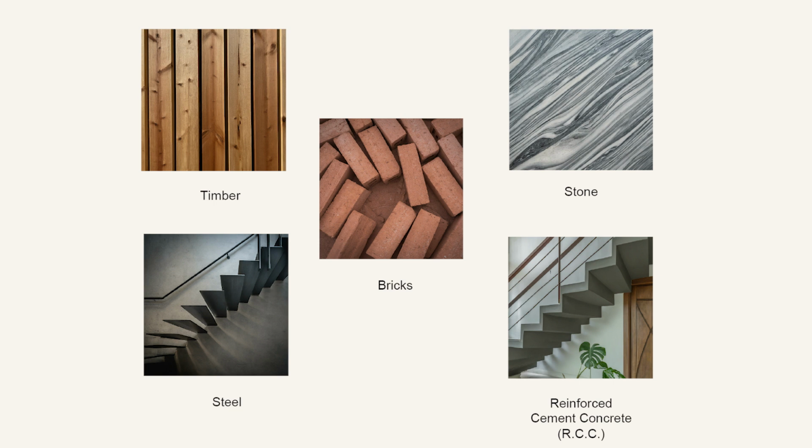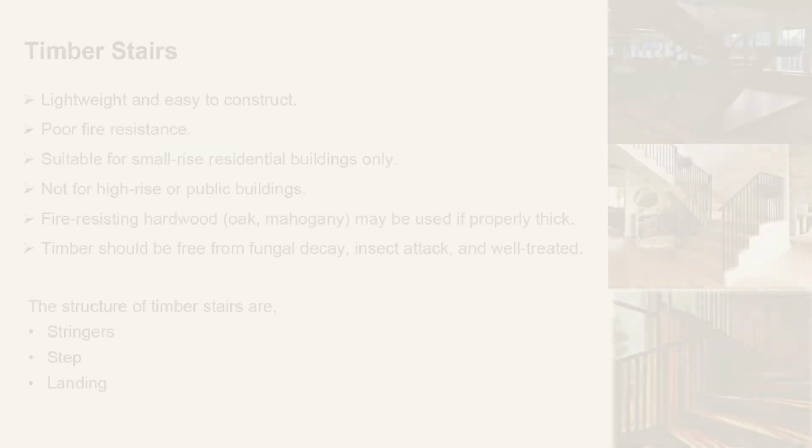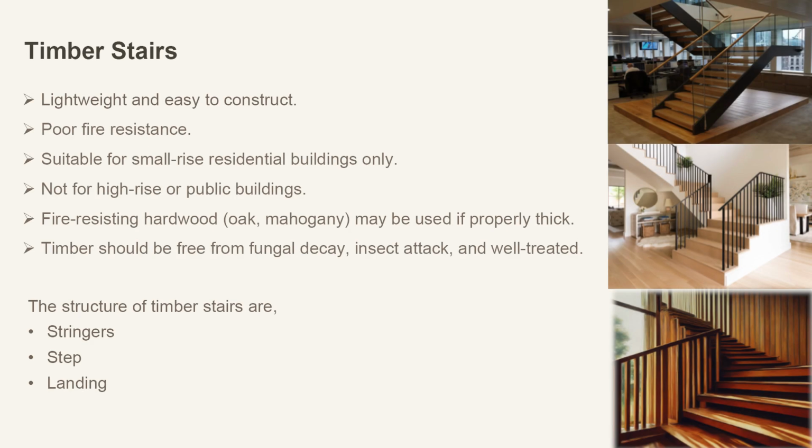First, let us talk about timber stairs. Timber stairs are lightweight and relatively easy to construct, which makes them a popular choice for many. However, there is a big catch. They have very poor fire resistance. Because of this, timber stairs are typically used only in small rise residential buildings and are unsuitable for high rise residential buildings or public buildings.